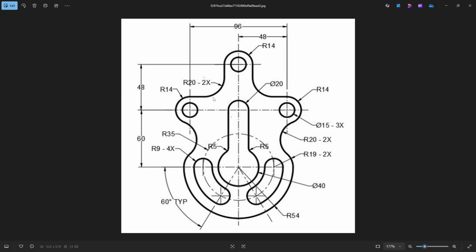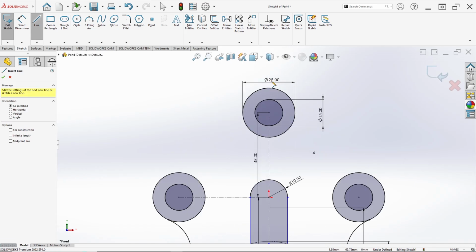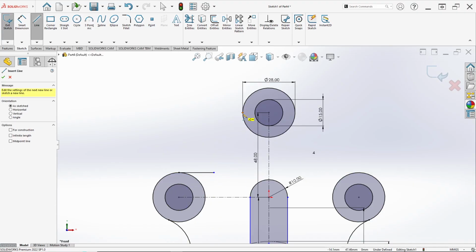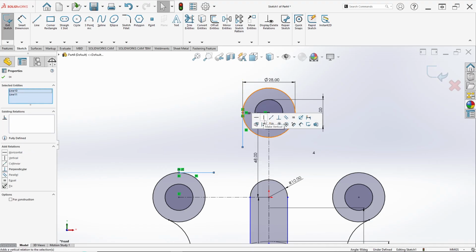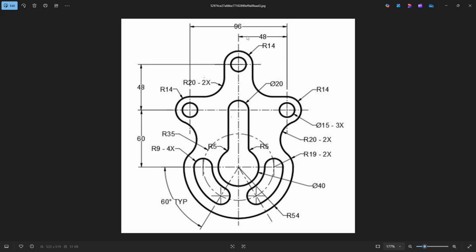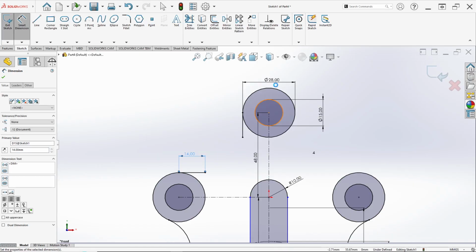Okay, and lastly we can make this sketch. Just simple. This has a diameter of 28. So we just make a line for this point. Make a line again for this point. Ensure this line and this line, we can select make equal, and set the line to 14 millimeter, because the diameter of the outer circle is 28.